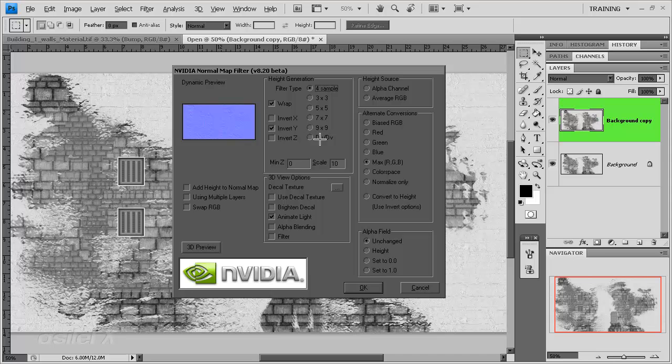One of the quick ways is to select the 4 sample. If you're using Cinema 4D, you do need to invert the Y, just to avoid having to hit the invert Y within Cinema. So if you are not using invert Y, you can just invert it directly in Cinema. I'm going to do it within the normal map because I have been using mostly Cinema, and some of the other applications I use basically the same setup.